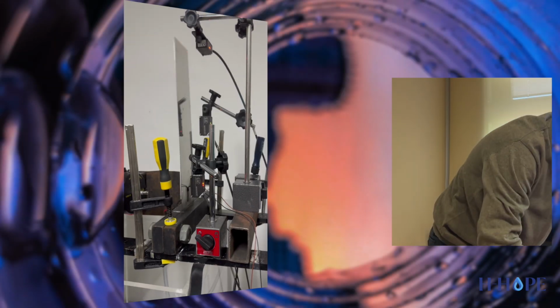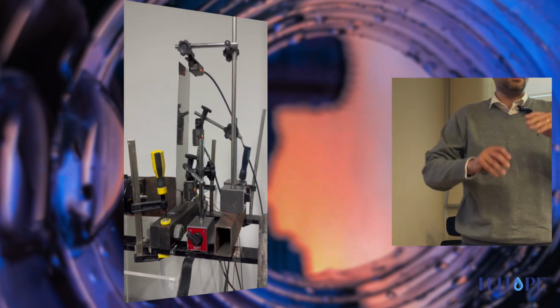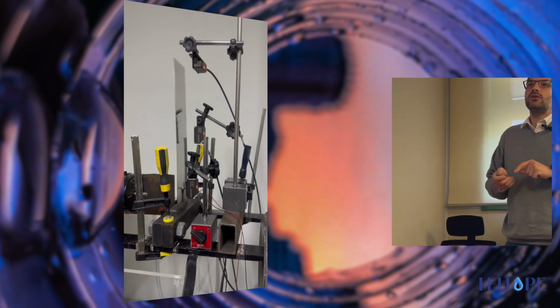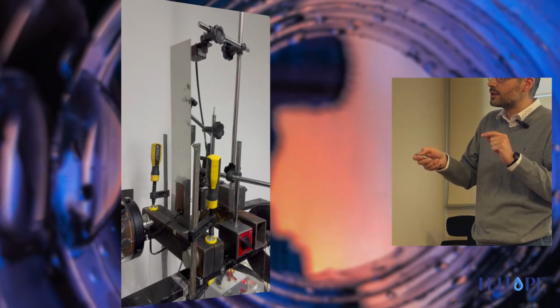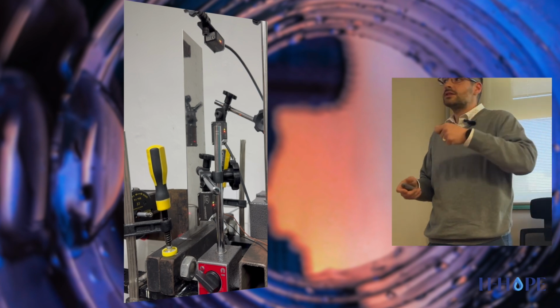What we will see in this video is our beam oscillating, and also where both piezoelectric patches are placed. This is the smallest one, and the other one is the biggest one. Remember, the smallest one has the polarization axis inside the plane of the patch. One of them we use to excite, and the other one to measure the output voltage.